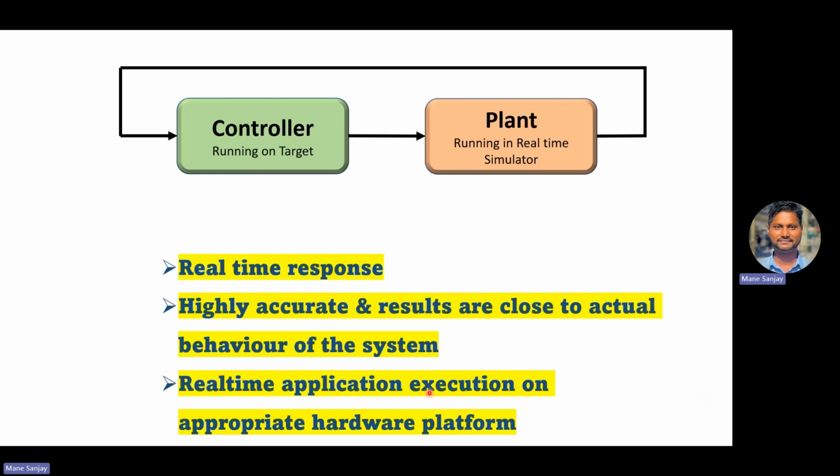So very simple. When it comes to hardware-in-loop simulation, you use a real-time simulator from different suppliers. There are different suppliers or manufacturers in the market like Opal-RT, National Instruments, or ETAS. They produce the real-time simulator where you can simulate analog signals, digital signals, PWM signal, CAN signal, analog, digital, PWM in and out.